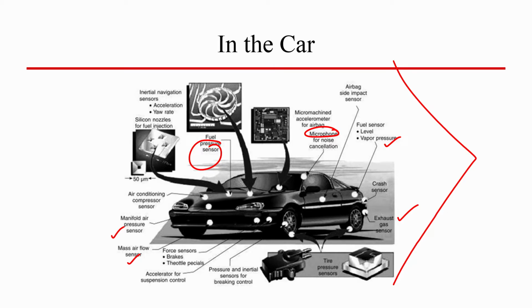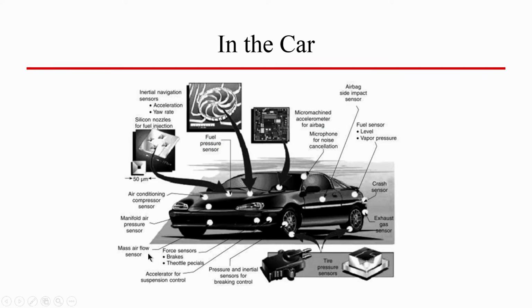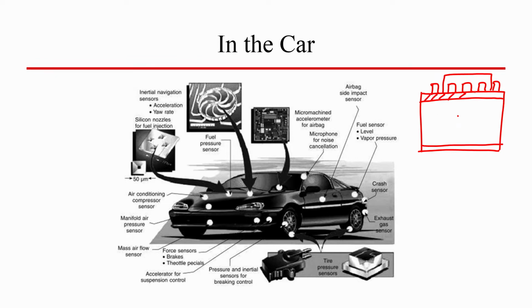Now, if we talk about gas sensors, it becomes very simple, and we have discussed it in one of the modules. If you want to design a gas sensor, what you require is that you should have a substrate, you should have the contact pads, and you should have the sensing material on the contact pads. If it is silicon, then we say that this is an oxidized silicon wafer.